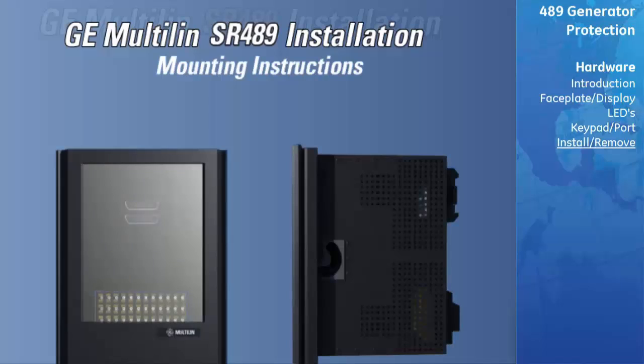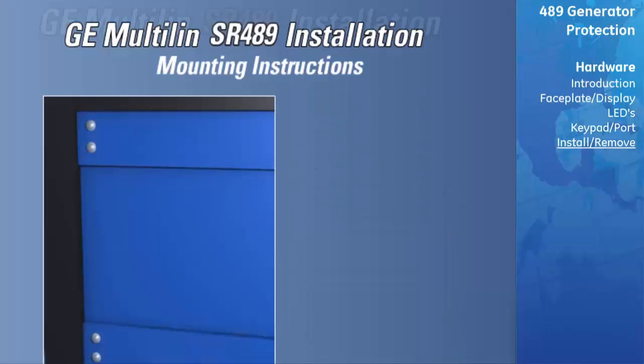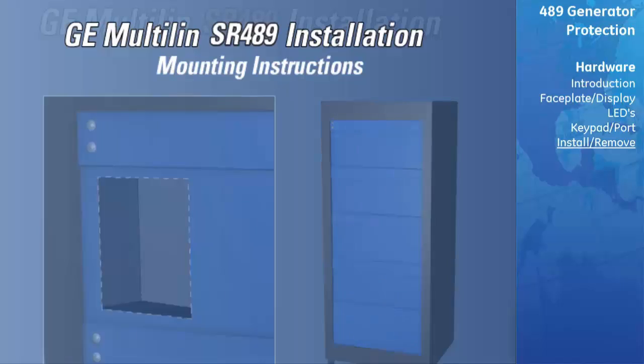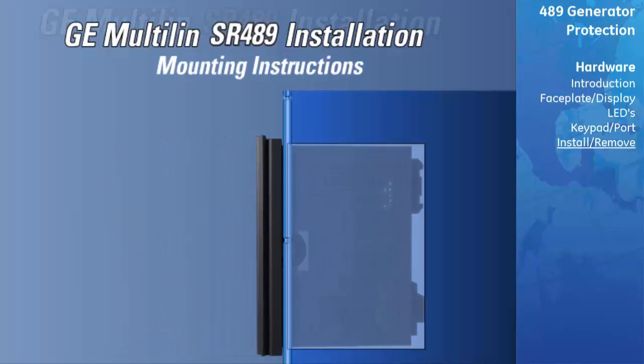Review the dimensions and location of the relay wiring before selecting a location within the panel that is appropriate for the relay. Cut the hole in the panel to the dimensions shown in the drawings. After the mounting hole in the panel has been prepared, slide the relay case into the panel from the front. Apply firm pressure on the front to ensure the front bezel fits snugly against the front of the panel.